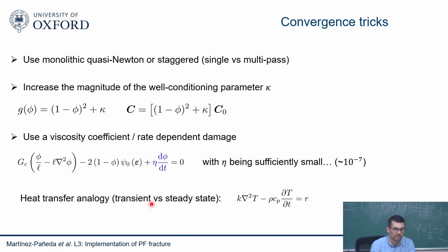The way you want to implement this, for example, in Abaqus, is that instead of picking a steady state heat transfer, you pick transient heat transfer. And then you have a problem like this. This is what Abaqus gives you. So you say again k equals 1. You again define your source term in the same way in the UMAT. But now you define the density, maybe equal to 1. And this heat capacity coefficient, you define it equal to whatever you think your eta value should be.